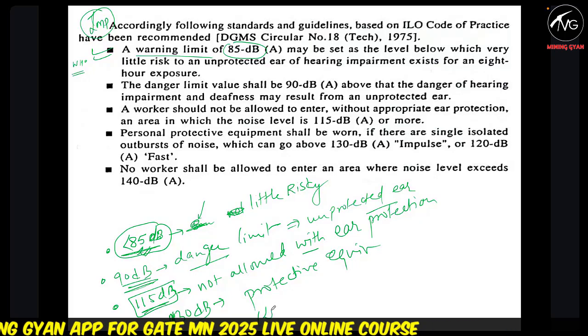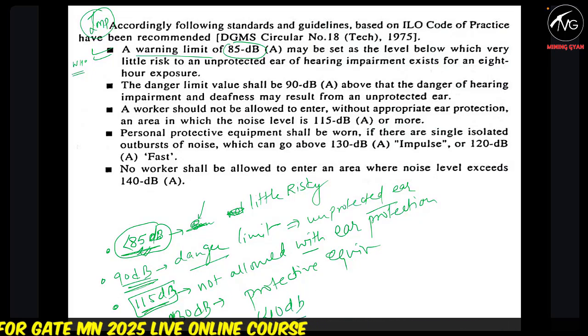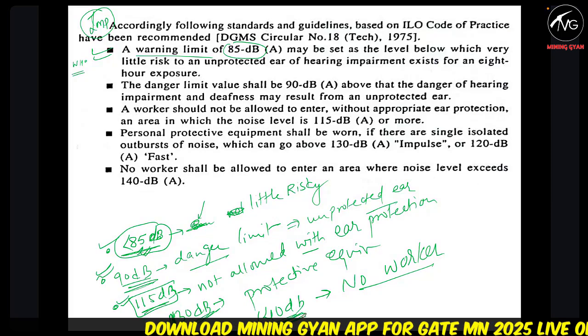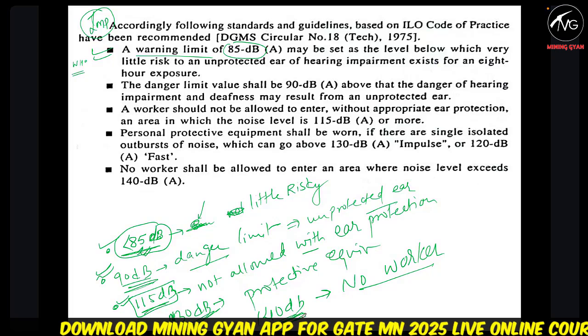And if the limit is 140 decibel, no worker allowed. If you are not wearing any protective equipment, you will not be allowed in that area. Just remember 85 decibel, 90 decibel, 115 decibel, 130 decibel, 140 decibel. These 5 points you should remember.